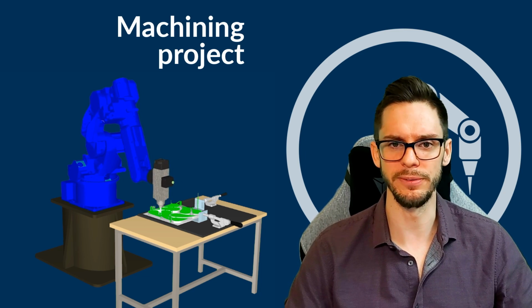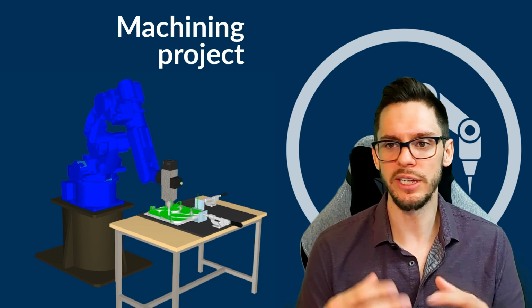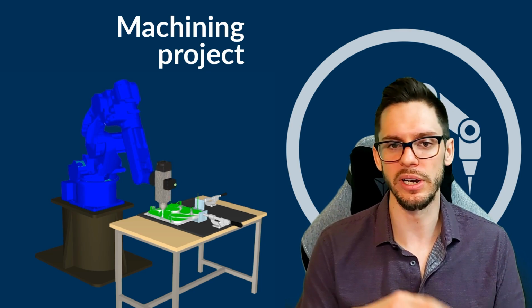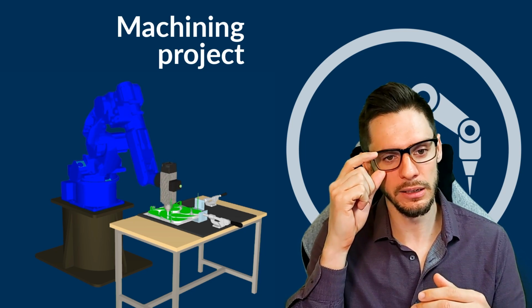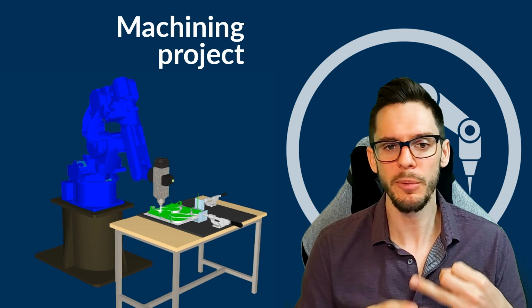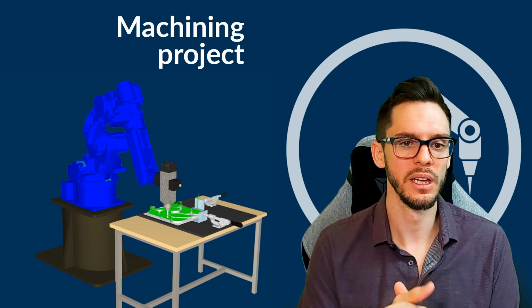So for example, if you have a CAM software and you created a milling project in it, you can generate your G-code-like file, so maybe an APT or NCI, for example, and drag and drop it to RoboDK to generate the machining project. Again, you can manage things like joint limits and singularities, but you can also manage tool change and spindle RPM if required.